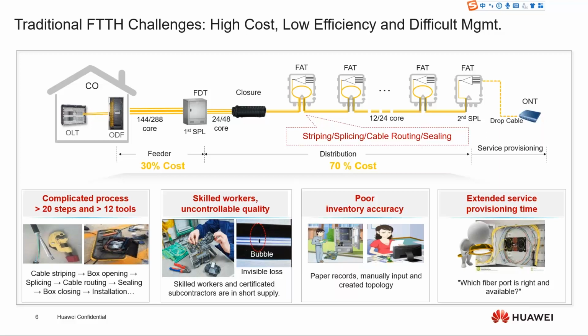First of all, I have to strip the cable and take out the fibers. During this process, I must pay attention to not hurt myself, because the cable strength part and jacket are very strong and difficult to remove, even using tools. Then, I need to strip and clean the fiber coating with strip tools and alcohol. I should be very careful because the fiber is very fragile.